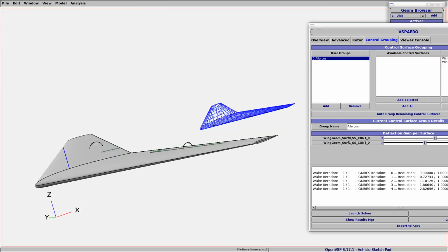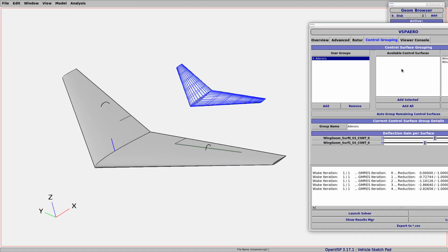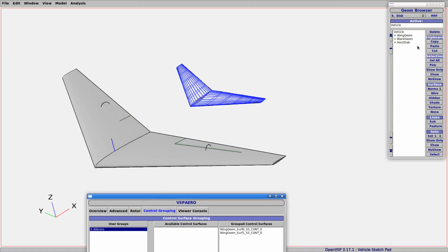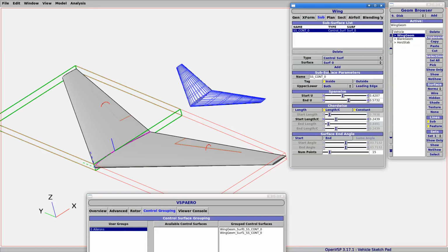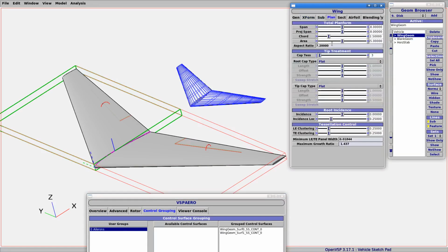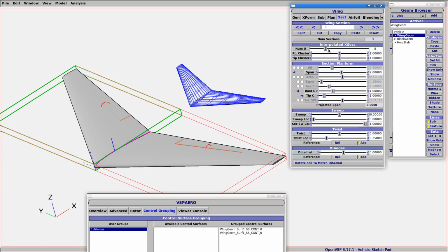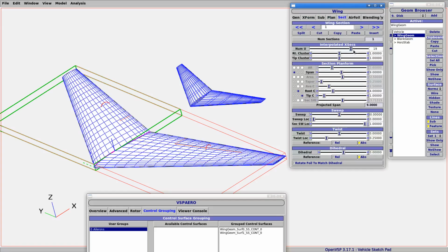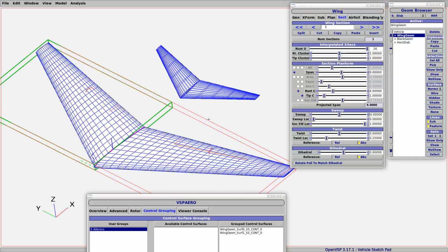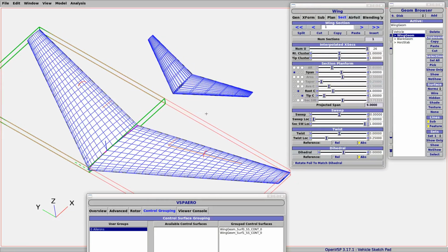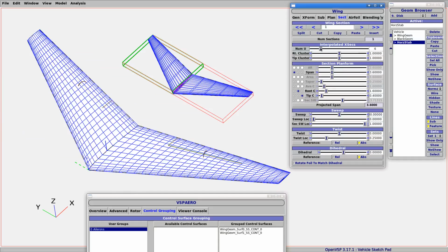Just see what happens when we run. So what I'll do is, for both of my wings, increase the number of horizontal divisions, or oh, it only goes up to 26. Is that right? Alright, this is going to slow the simulation down quite a lot. I will also do it for our horizontal stabilizer as well.